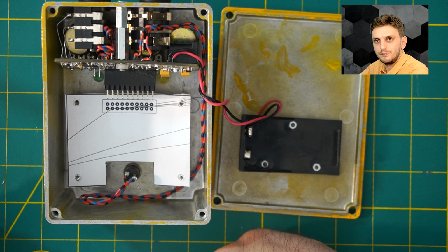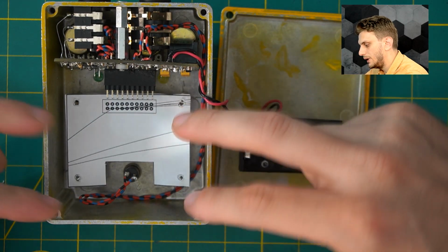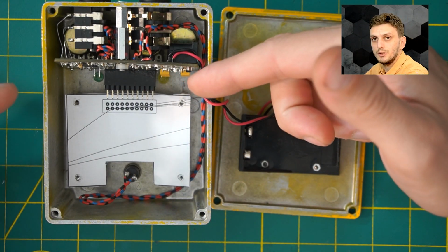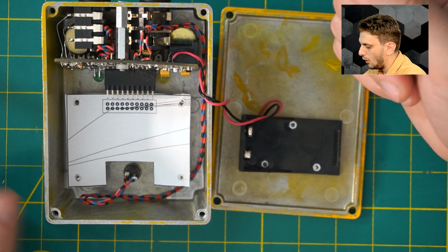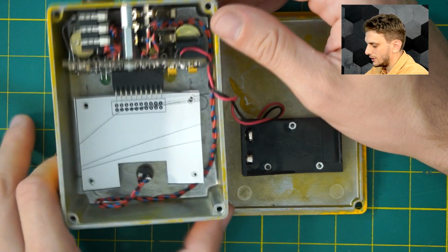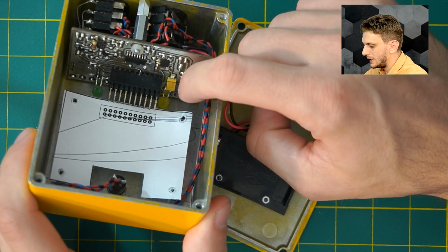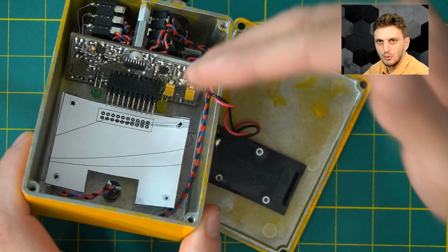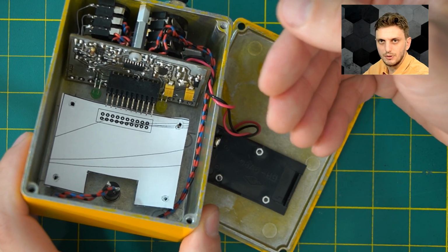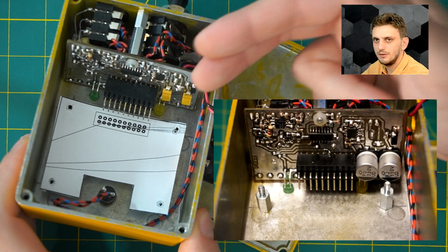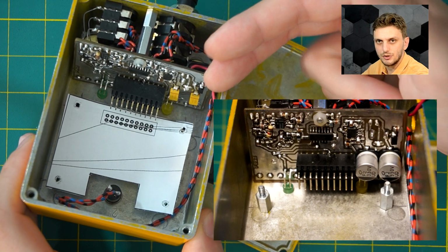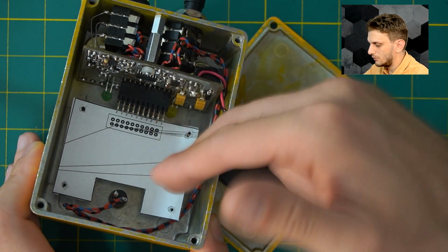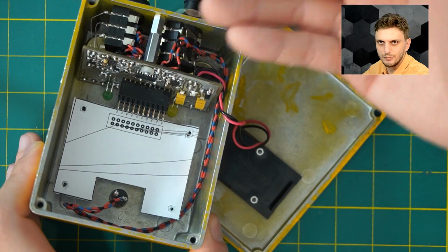They're not very good. So what I'll have to do is increase the board size a bit so that the connector can actually get onto the board so we can have our interconnections. And because of the increased board size, one of the other things that I had to do was to make these capacitors much smaller. So here you can see that I already placed in my new low profile capacitors. These are a couple tantalum capacitors. Previously these were large electrolytic capacitors, so they were very tall and they were too close to the second board, so they would end up hitting, and that would not be a good thing.